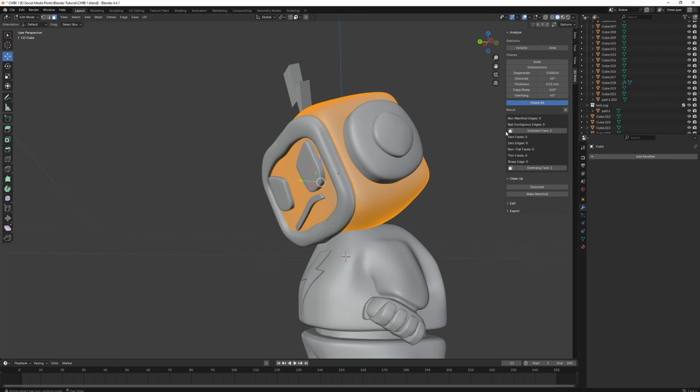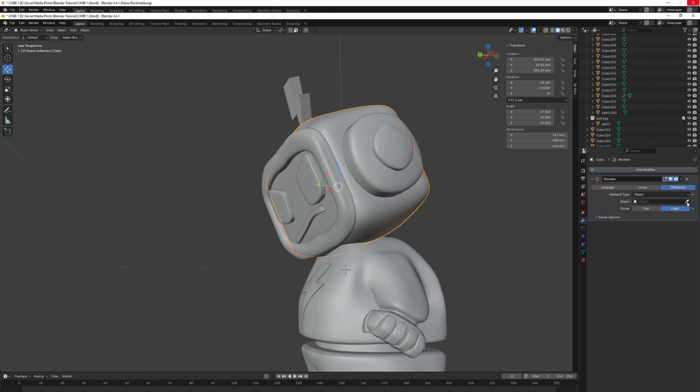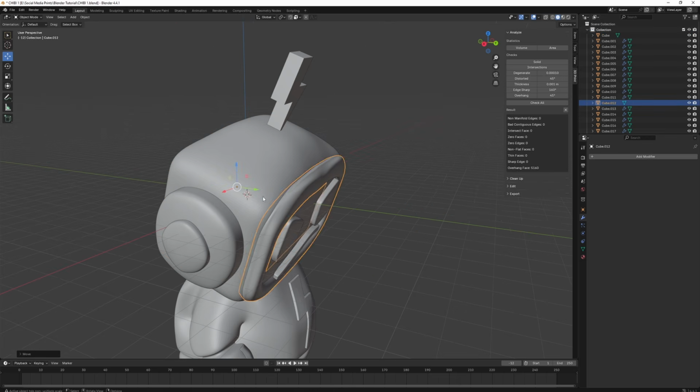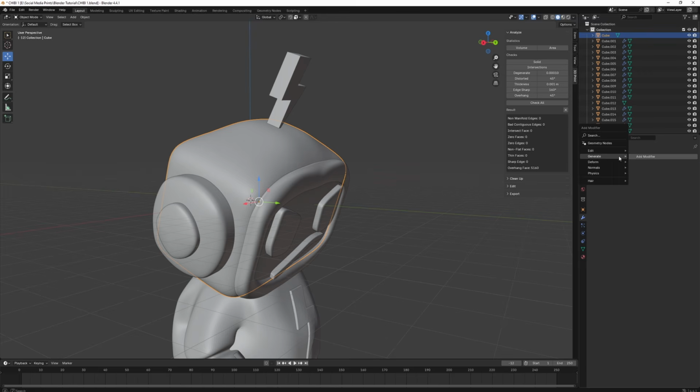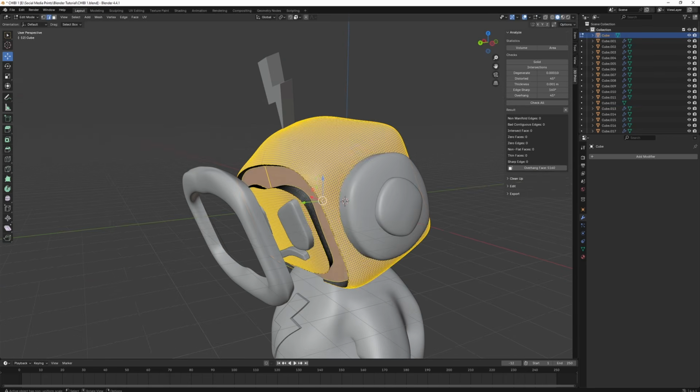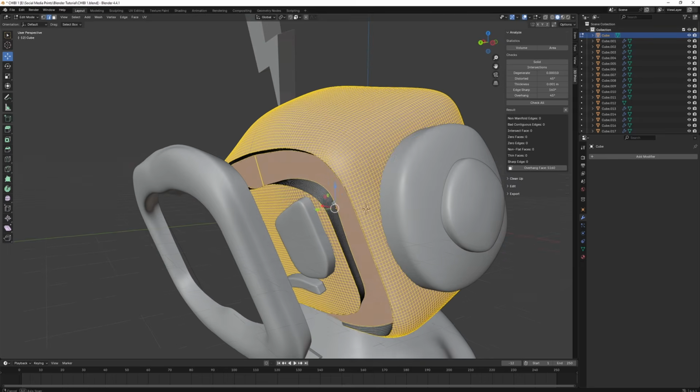Now we can do the same thing for all of the other parts. Using the exact solver works pretty well, but if it doesn't, choose fast, and if that doesn't work, then something is wrong with one of the meshes. Check the 3D Print Toolbox again. Also, always make sure that the part that is actually going to slot into another will be able to fit. Boolean modifiers just carve exactly as the object looks. There is no guarantee that it will fit the part if it's curved enough. So in some cases, it is best that the part to slot in is flat on every side.